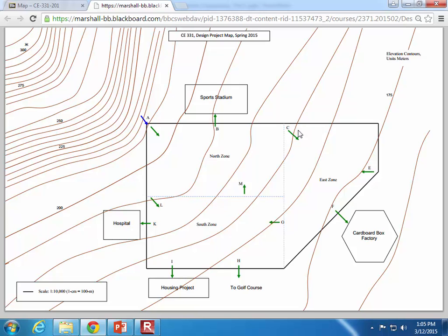You can. As long as you're using the same offset at each location, that's fine. So if you use the surface elevation for everyone, that's fine. Or if you want to use 1 meter under the surface elevation, that's fine. But specify in your accompanying calculation and explanation what you did. Okay. Any other questions?